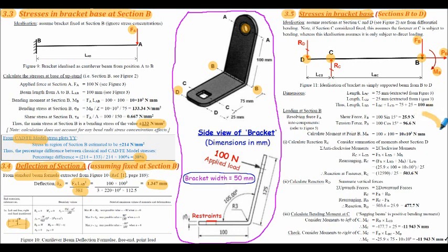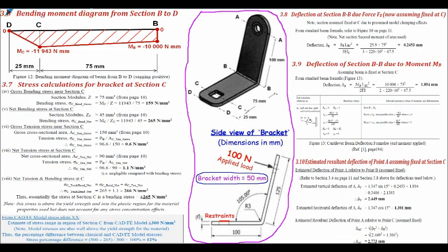Calculation for the loading, shown here. Again, I realise this is difficult to read, but if you do want to read and follow the calculation in detail, remember there is an enlarged view of this report towards the end of the presentation. Using the principle of summation of moments, I calculate reaction RC. Using the upwards and downwards force equilibrium equation, I calculate reaction RD. And then I can calculate the bending moment at C, which I've actually undertaken using two calculations, calculating moments to the left of point C and then calculating moments to the right of point C. And of course I get the same value, which I should, because that shows my beam idealisation is in equilibrium.